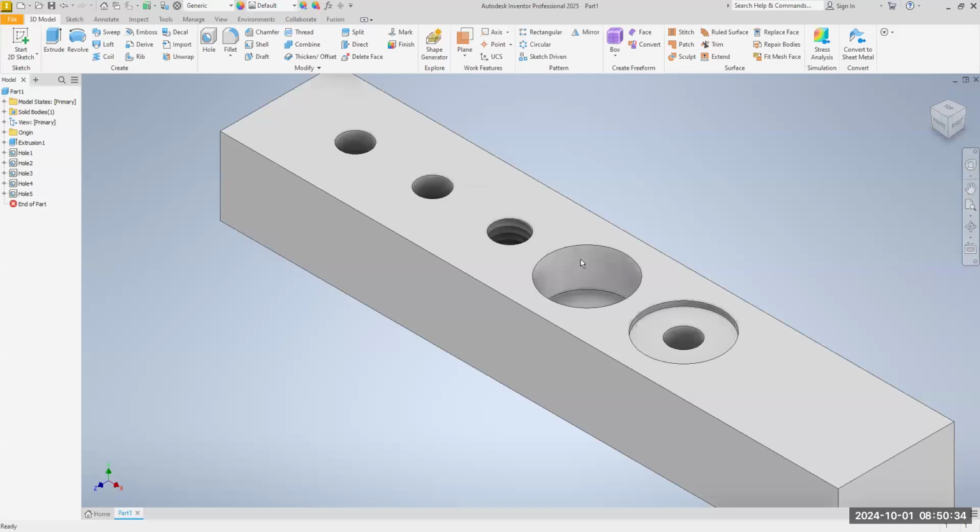All right, now that's like a 1/2 inch deep. That should be sufficient to recess the head of our bolt or screw. So you see the difference between them, they look alike, but they're not the same. This one will recess the head of the screw. This one just makes a nice, flat, smooth surface so that the underside of the head of your bolt or screw will seat properly.